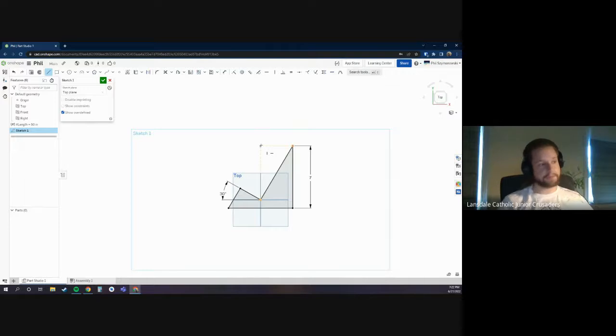But sometimes you don't want them. Like maybe I want to make this line not right there. Well, now that I've already made it, I have an option to either just delete those two constraints, or I could instead just delete the entire line and start over again without mousing over the points. Now we won't have implied constraints. So implied constraints are helpful. They help save time, and they assume that you want constraints in certain places, but sometimes you don't want constraints there. So just be aware of that.